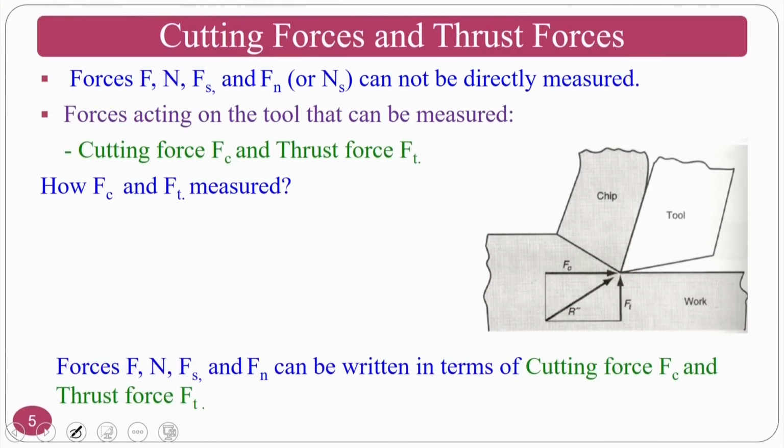Okay. So, the forces F, that is the frictional force, the force normal to the frictional force, the shear force, and the force normal to the shear force, these are all not calculated directly. Okay. These are all obtained from a force relation, which we will see in the upcoming slides, which is nothing but the Merchant circle relation.